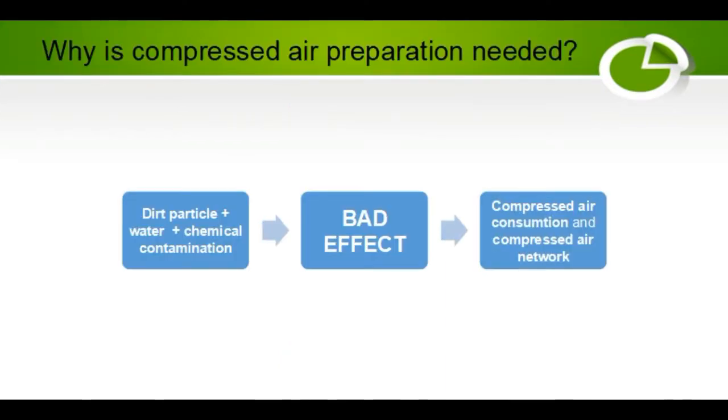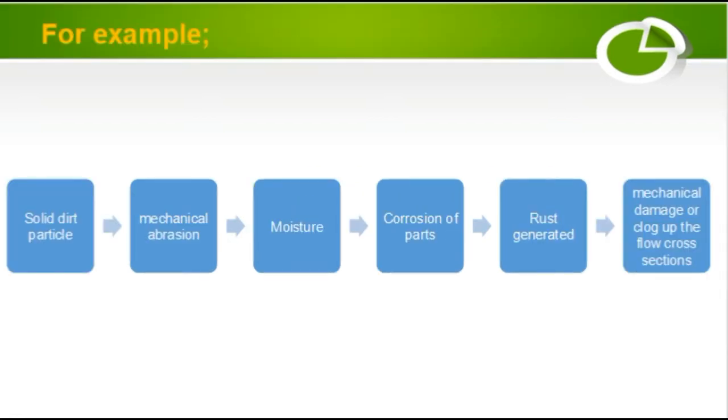Why is compressed air preparation needed? Particle, water and chemical contamination will cause bad effects. This will also affect compressed air consumption, and the compressed air network will not be efficient. This is an example of the bad effects. Solid particles will cause mechanical abrasion, and moisture will cause corrosion of parts and the parts will rust. This will damage the mechanics or clog up the flow cross section.